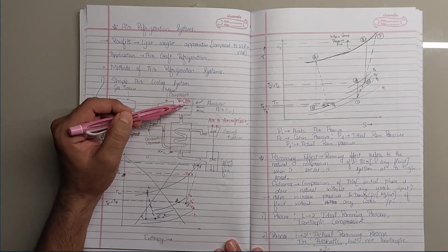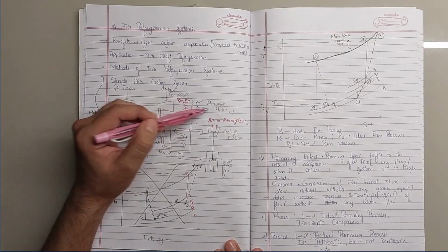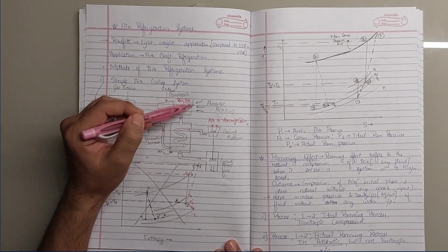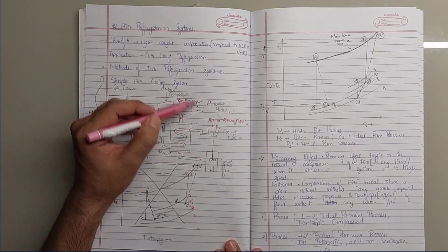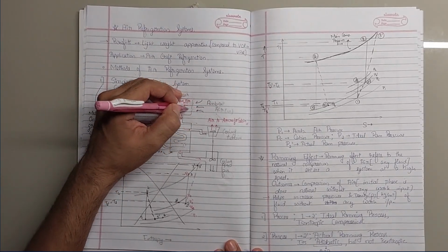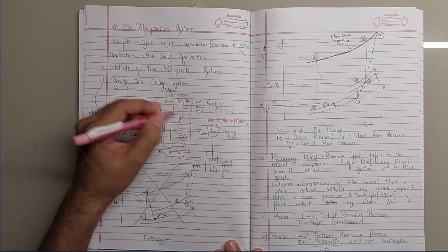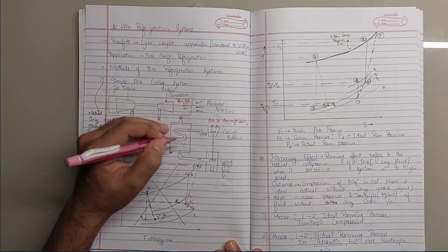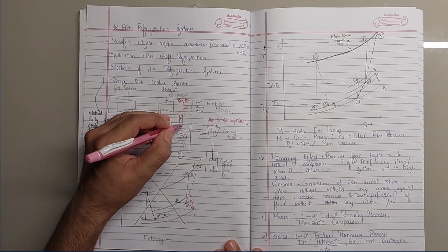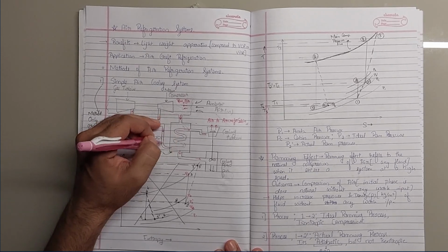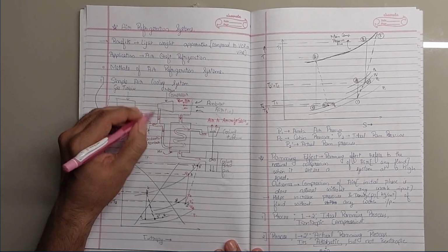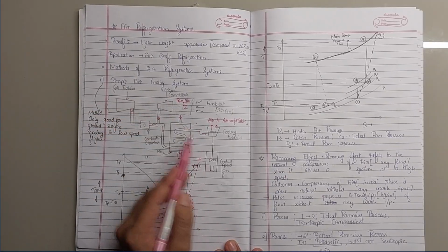Inside the shell, the newly inputted rammed air, which is very cool, just atmospheric air, is admitted, and the hot air goes into the tube. So this cool air takes energy out of the hot air and makes the air from the main compressor cool.